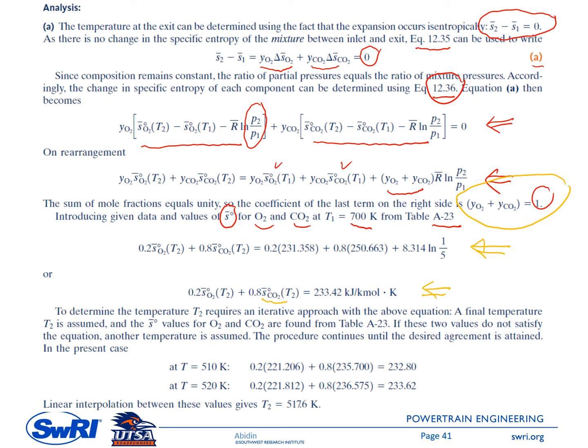The best way is you grab maybe one extreme value and the other one from the other side, and then you can do a kind of numerical method there. I'm not sure whether you already took numerical method when you took this THERMO 2, and then you can use a bracketing method to get the correct T2.